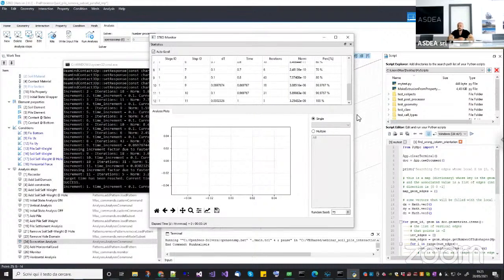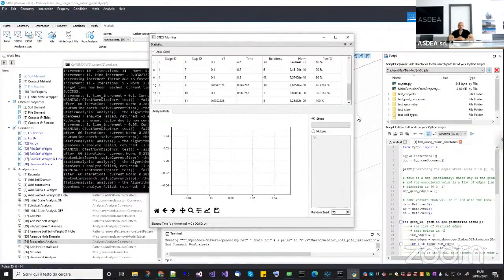Anyway. Can we use the new contact element with brick UP element? Yes, you can, because the beam contact 3D requires 3 dofs in the node. The new contact element actually is already available for any kind of dof set. So it can have just displacement rotation, or displacement pressure. So yes, you will be able to do it.